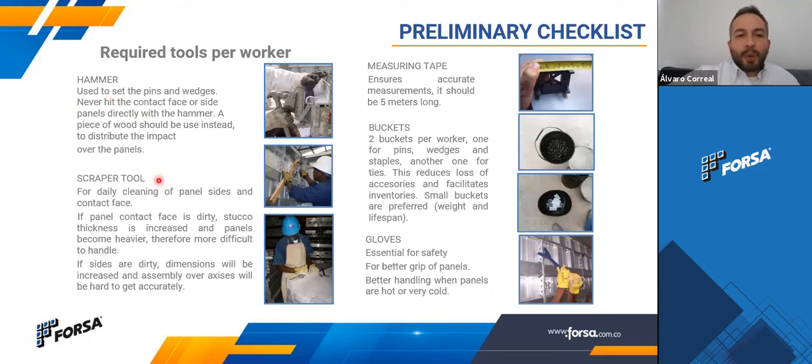A scraper tool, because it's very important to keep the set and the formworks clean every day. That way you guarantee that the finishing is the optimal one, and you're going to save money on the final stage, which is the painting stage.